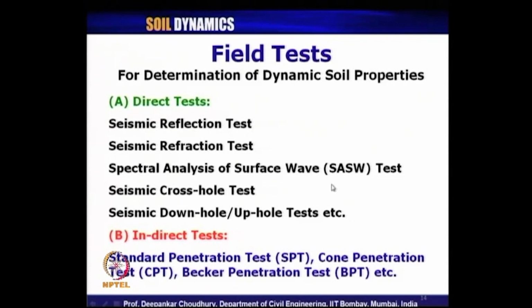So, that is why MASW, but the methodology of the testing and principle everything remains same, only difference is instead of a single channel we use multi-channel. So, that is why MASW also you can note down with this. Then another direct test is called seismic cross hole test, and another one is called seismic downhole or uphole test. So, these are the different types of direct field test for determination of dynamic soil properties.